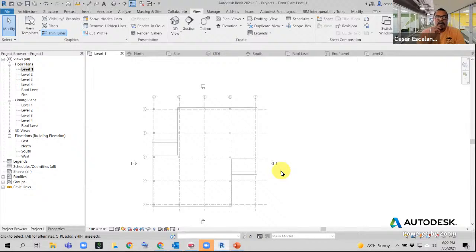And so having a robust set of view templates is fundamental for Revit to display correctly the information needed in the final set. In fact, view templates are sort of sacred. I mean, you're actually compromising how things are going to be displayed in the final sheets.